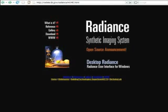Now, a small amount of background about the history of HDRIs. A gentleman by the name of Greg Ward created a render engine back in 1985 called Radiance, and this renderer used the concept of high dynamic range imaging where illumination in a scene is calculated and stored as an unrestricted or open-ended value rather than as a fraction from 0.0 to 1.0 or as a value from 0 to 255 like those typical 8-bit images we see every day on our computers. His render engine specified the first high dynamic range image format, and for many years this was the only one. Today there are a few more.